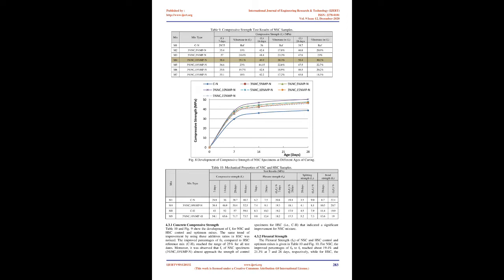Generally, it was observed that the optimum ratio for NC, regardless of the dispersion technique, was 5%, which enhanced FC at 7 and 28 days. However, increasing the NC ratio in mortar over 5% led to less enhancement in FC at 7 days, while diminishing FC at 28 days for all dispersion techniques.